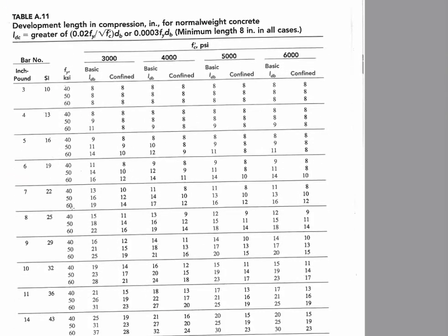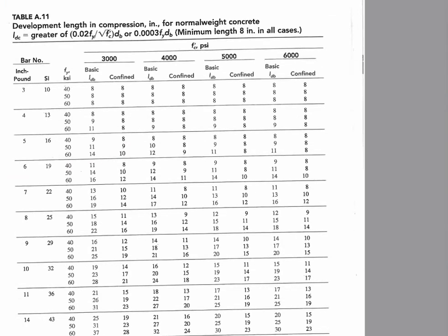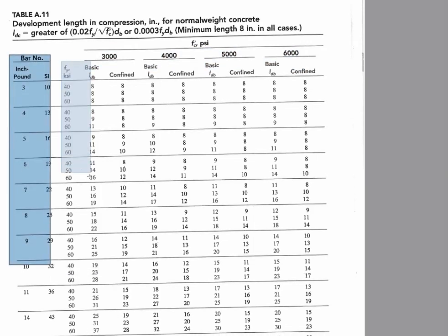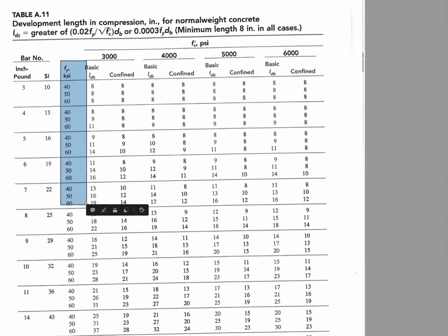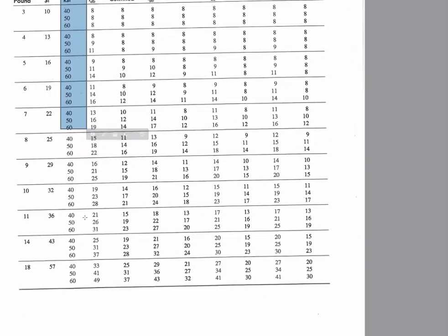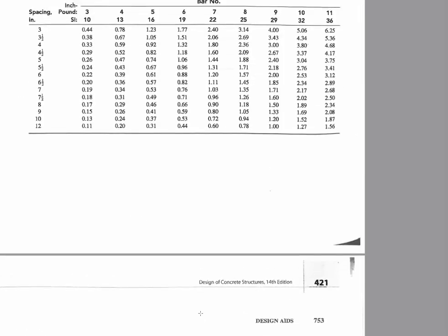And then we have development length in compression, which would be required in the vicinity of connecting to a column. And we'll get around to that with the design. But again, function of compressive strength of concrete, function of bar size, and function of steel strength. So it's just a matter of finding your way through these tables and saying, that's my parameter, that's my minimum, that's my parameter. It falls into place quite readily, I'll say. I don't want to trivialize the content, but it does turn into somewhat of a cookbook type process.